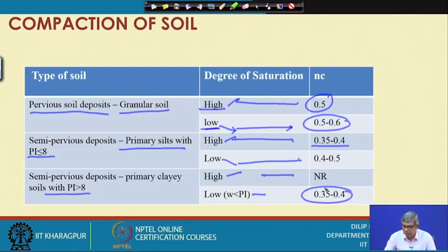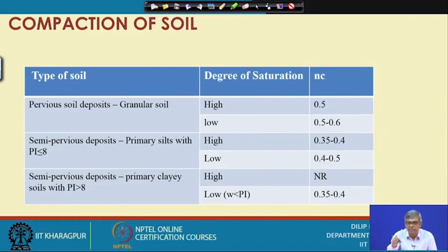So, these NC values can be taken for calculating and deciding whether the depth of improvement is suitable for the particular weight and height. If it is not, we can change the weight and height to adjust to the requirement.